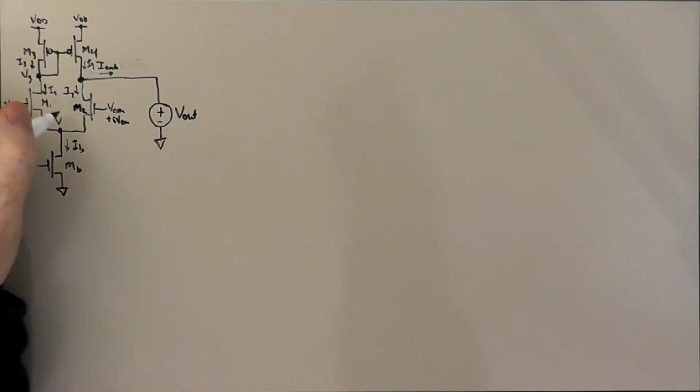of this diff pair. Well, if I were to put a delta VCM on both sides of this diff pair, I will move this common source node voltage up by a little bit, delta V. We talked about these two transistors, M1 and M2.